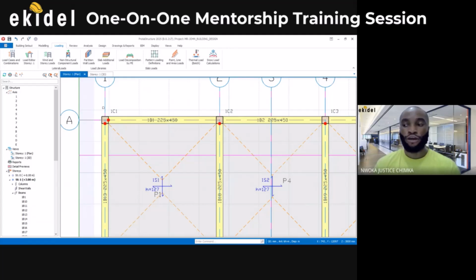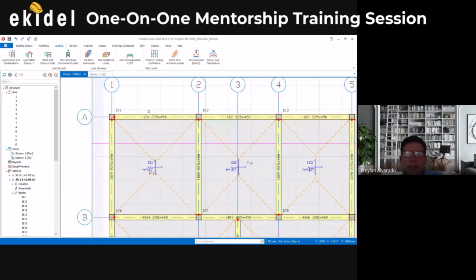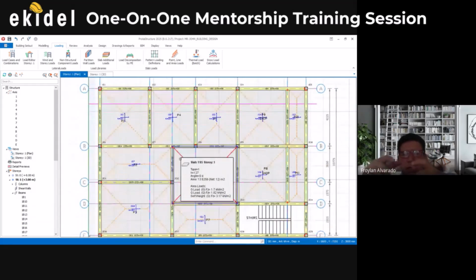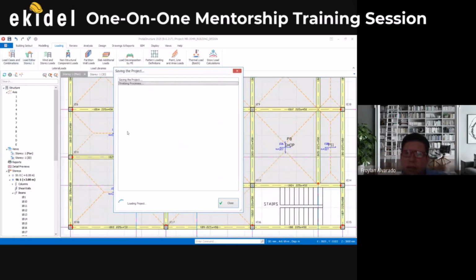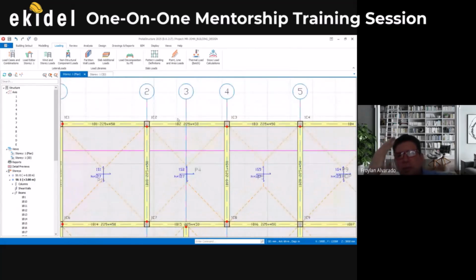If I'm designing a building that will require earthquake or seismic load, I will not apply hinge on it because I need the joint to be stiff. Exactly. So when you're looking at global torsion of the building itself, you would need to contemplate whether or not the building needs that rigidity. In that case, maybe you would need to pin it again so that it doesn't have hinge ends.